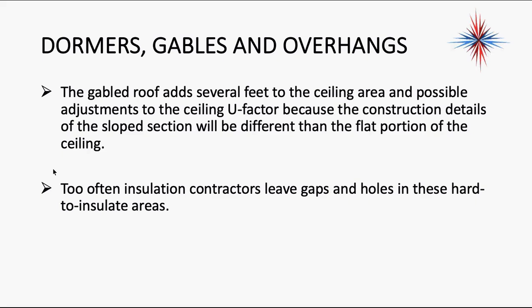You could get up on a ladder and feel the ceiling on a cold day, or a hot day, to see if it feels cold or hot. But there's another easy way on a winter day to tell if that insulation is missing. Should there be snow on the roof? There should be, yeah. If it's not, then the heat's up there, melting the snow.